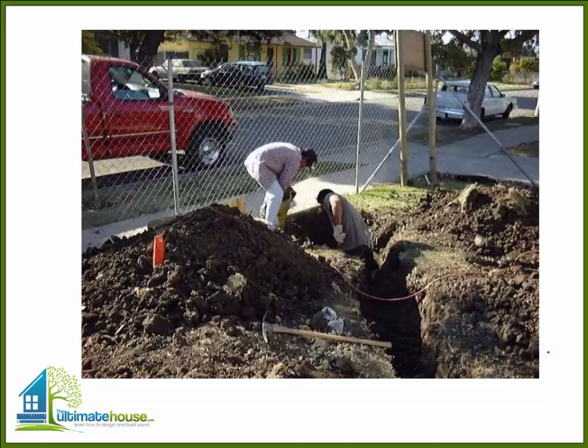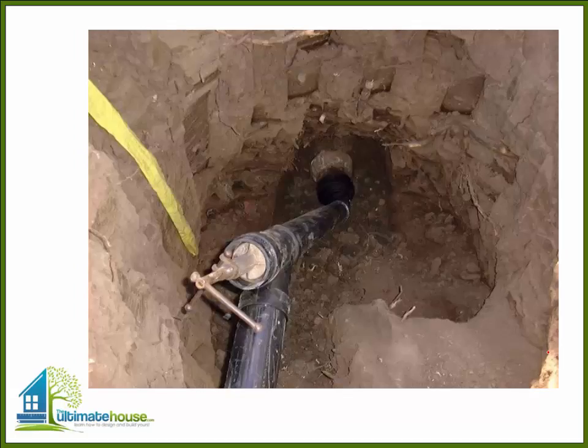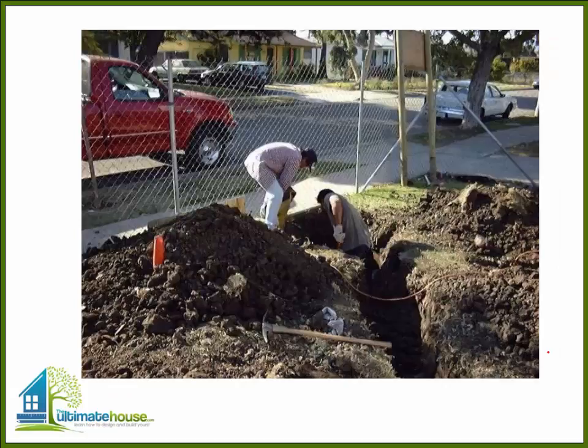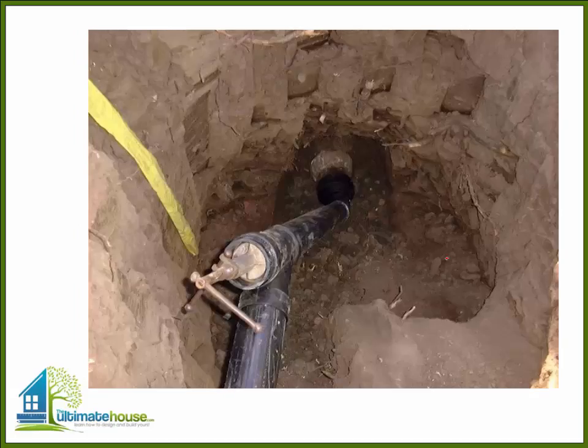And an important thing to think of with remodeling is your utilities and all of your water lines, gas lines, sewer lines. We replaced all of that stuff in this little house. Sewer lines go about 5 feet deep. That's why these guys are digging so low to reach the city sewer, and that requires a special permit and special inspections to do a sewer line.